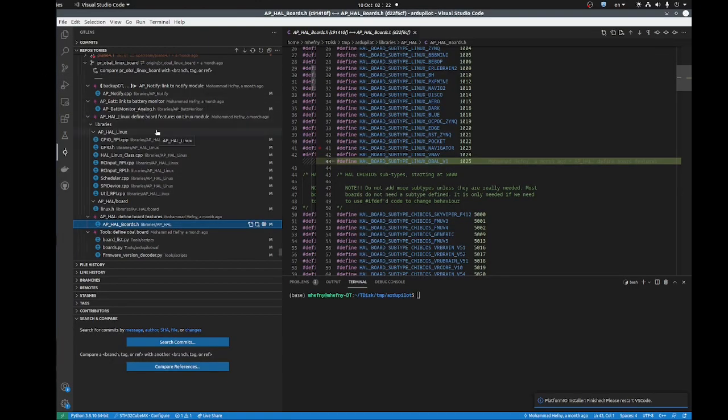Okay, here it is, the Ardupilot code. We will change some files. These files are the files that you need to access in order to define your own board. For sure, if your board is more complex, maybe you will need to access more files, but these files are covering already most of the things you will need to define a board that runs Ardupilot.